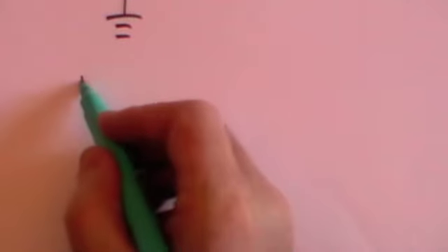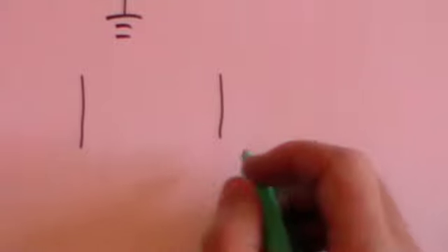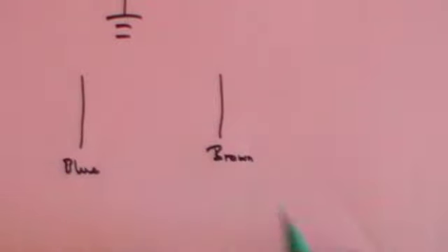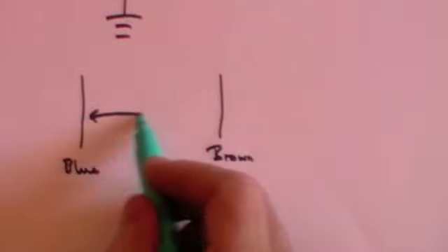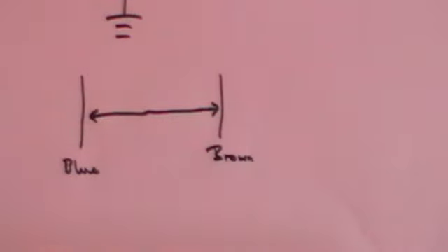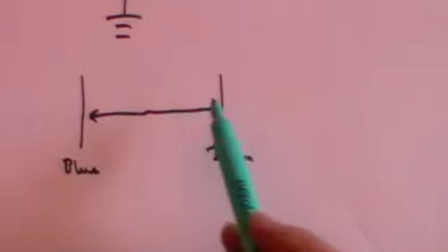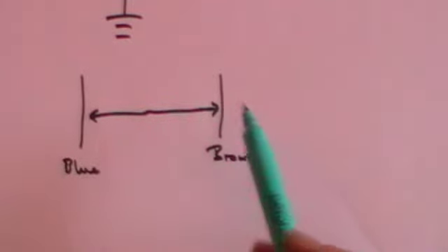and the electricity comes on. Generally speaking, the way that this works is that, of course, as we've said, there's the brown wire, which is the live wire, and the blue wire, which is the neutral wire, and alternating current is, of course, flowing backwards and forwards through these two wires. And what the residual circuit breaker is capable of doing is checking the difference between the levels of the current that is flowing. Ordinarily, if everything is going right, there shouldn't be any difference because this is just the same current alternating between the two wires.